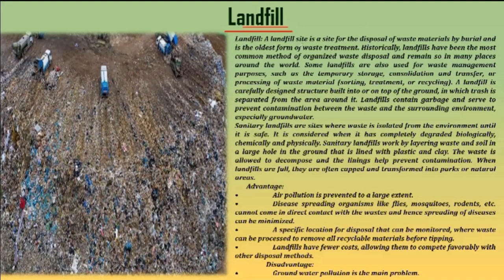See, first of all, you choose a piece of land around 4 to 5 kilometers away from the locality, right? The land should be low. After that you dig a big pit inside the land, and then make the bottom of that pit cemented, right? Make it concrete. So what will happen? The waste dumped inside the landfill will never come in contact with the groundwater, because once it does, a serious epidemic like cholera and diarrhea may come.